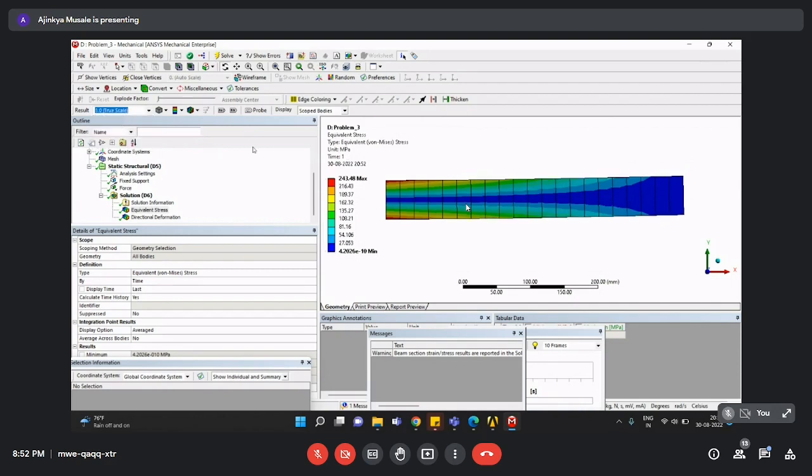Second is true scale. True scale means whatever values are present over here, according to that my model will look. So this is nothing but true scale. And again, I have some factors applied to that. So factors applied to my true scale, maybe 1.8. So whatever value is there here, 243, so 243 into this 1.8, whatever will come will be shown over here. So this is only for my visualization purpose.